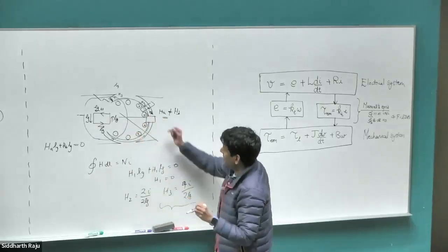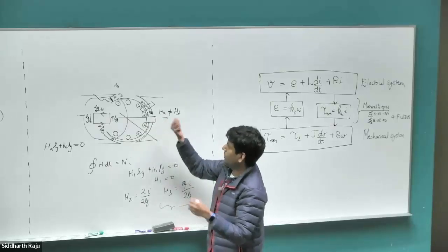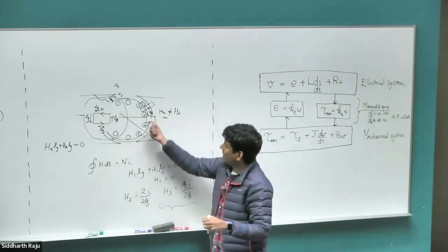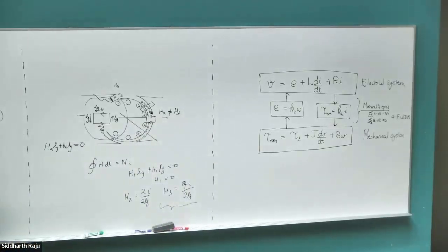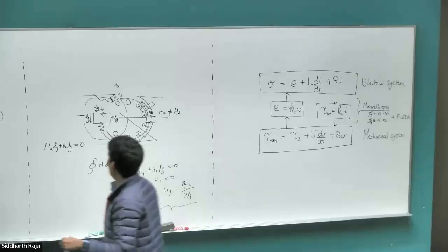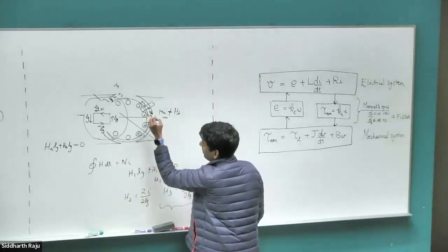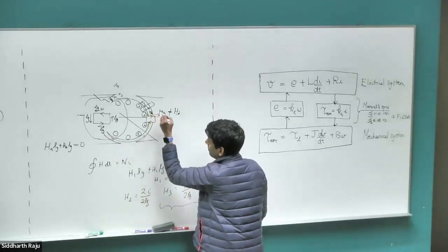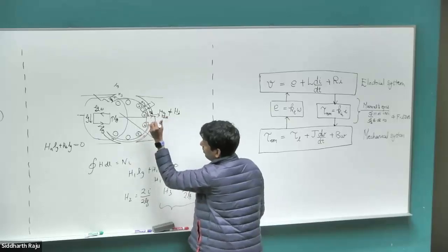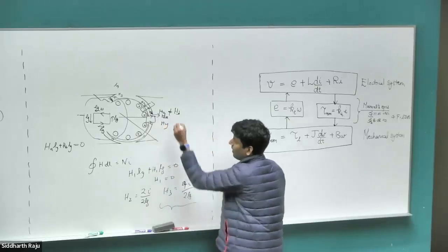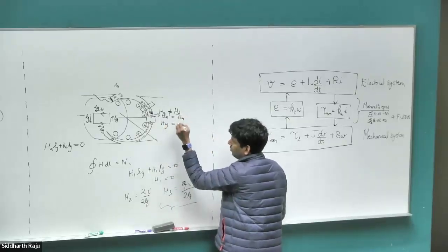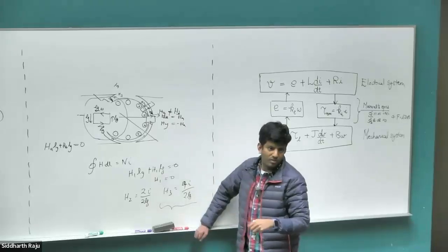If you look at this at angle alpha equal to 0, this would be this direction, right? The top one, at angle alpha equal to 0, the one going for alpha positive is the positive edge, the one going negative is the negative edge. So the way I've drawn, the H will come here such that this is some Hx, and this I draw in the same direction and call it Hy. And if this is equal to HA, this would end up coming out to be negative HA.